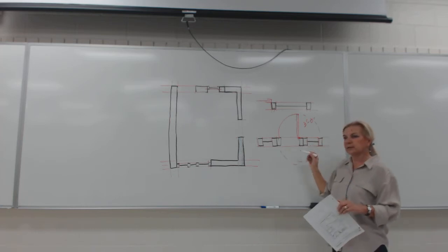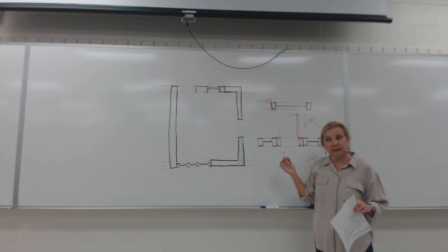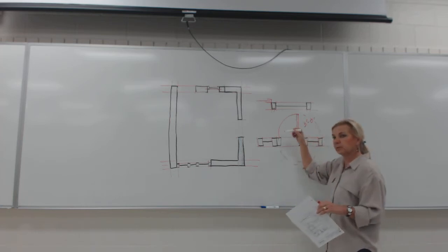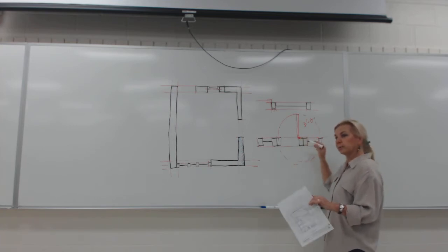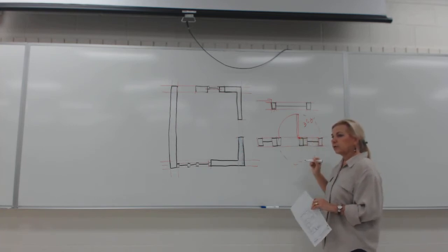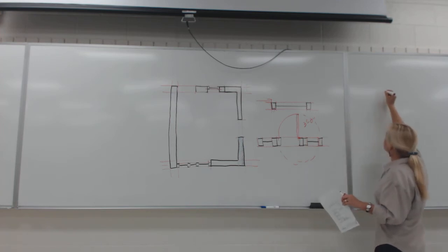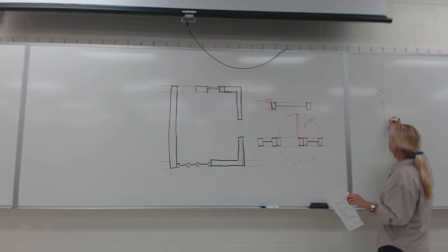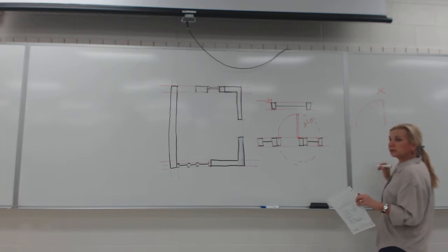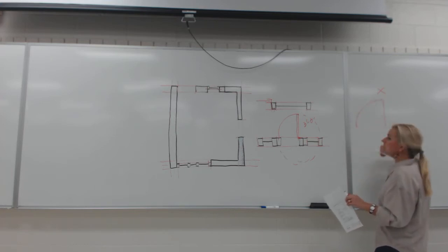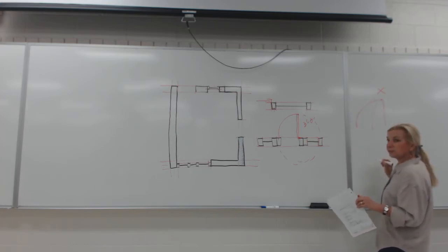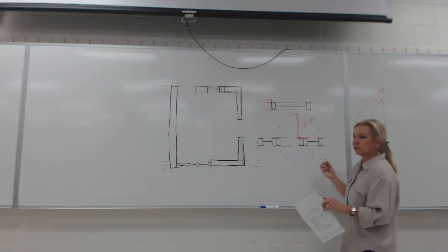So in AutoCAD, you would make a block and you would draw either a 3-point arc or a circle and trim it. What we don't want to see on the drawing is a door that, so this is no. The no is a door that does not have the perfect curve or too shallow of the curve. So those are not good looking doors.